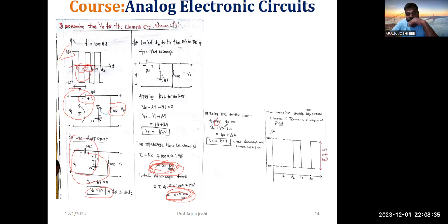We know the value of VI and the 4 volts reference value. VC is equal to VI plus 25, during the negative half cycle minus 25. So take 4 volts input, plus 25, total 29. Now the capacitor holds its entire charge and remains charged at 29 volts. You need to write the graph.